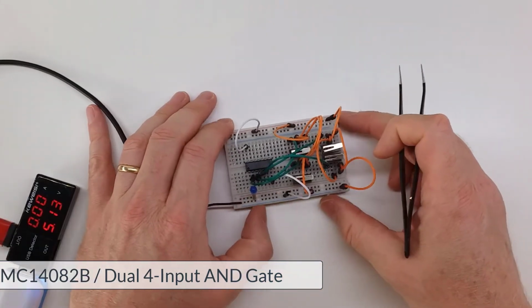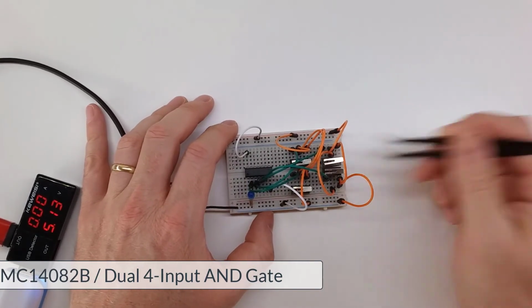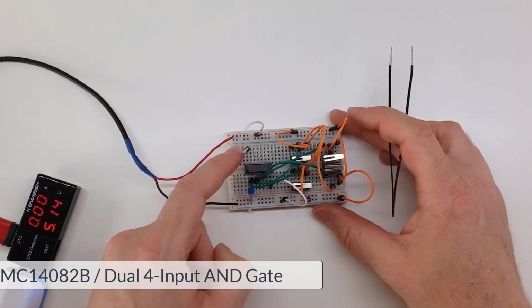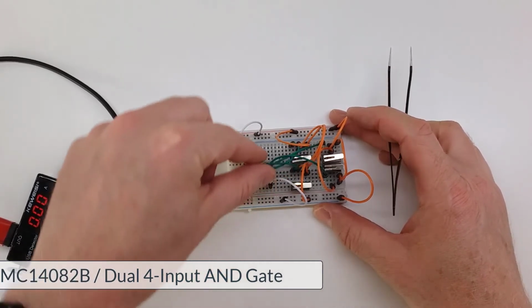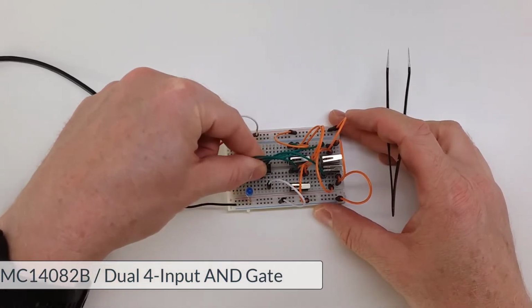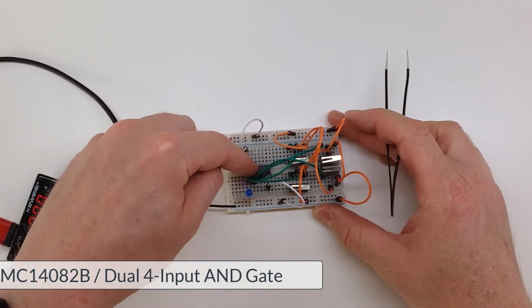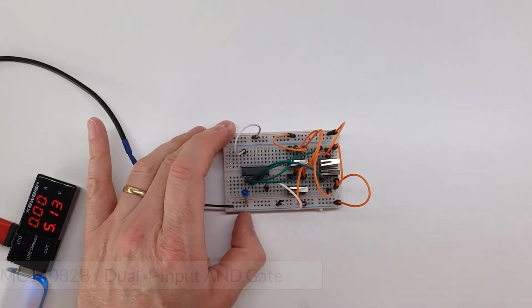All right, I've got this wired up on this breadboard. It's a little bit more of a mess versus the other ones, mostly because I've got 4 switches and each one of them needs 3 wires. And right here, I've got that dual 4 input chip, and they're kind of color coded. So I've got my 4 green wires, which are my inputs, and those are going into pins 2, 3, 4, and 5. And then I've got my blue LED on pin 1, which is my output.